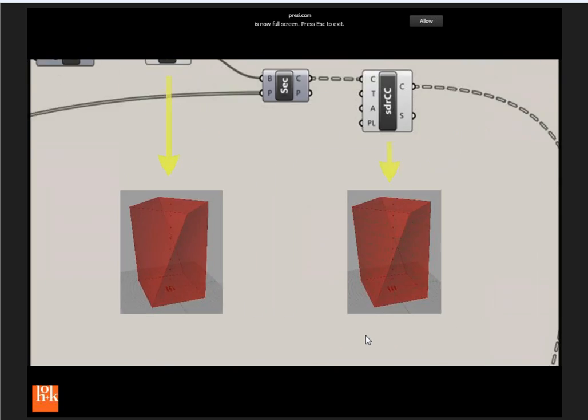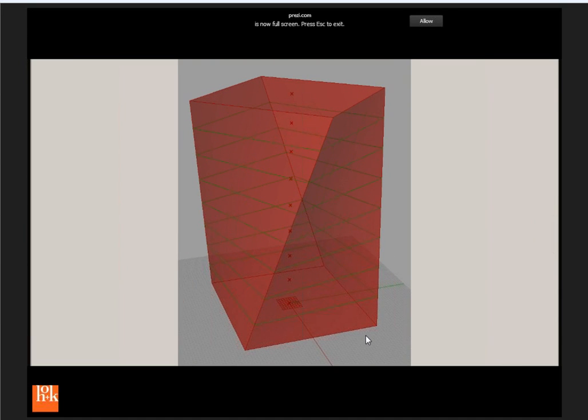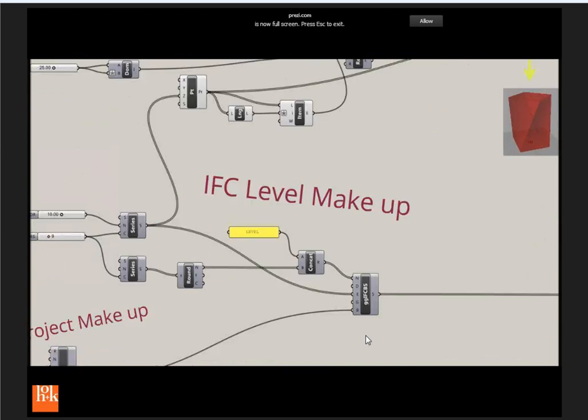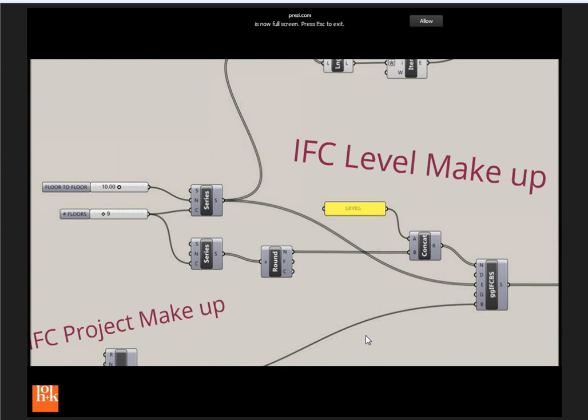And what I'm going to do is divide that. Sorry, so now I have edges for my slabs. What we're doing is a slab example here. So that's my slab edges. And then from there, I've got to give them something to sit on in Revit. So I'm going to give them some levels to sit on. That's pretty easy to develop.